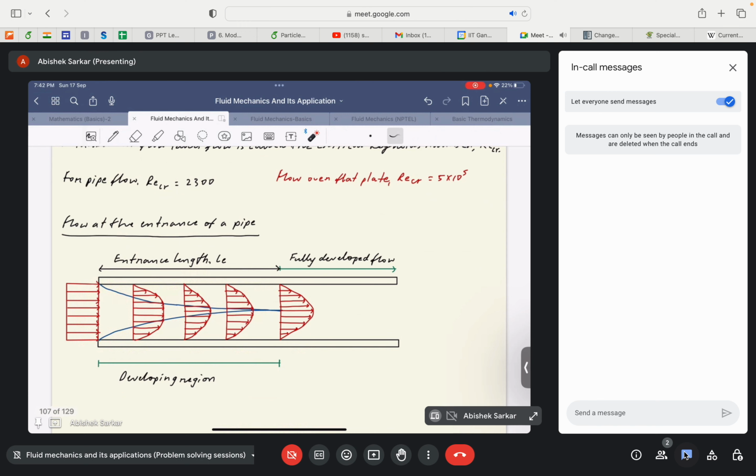So we can ideally say that in this region the viscous effects of the flow can be considered quite low, mainly because the velocity gradients would be quite low in those regions. So the viscous effects of flow are not manifested in this potential flow region.